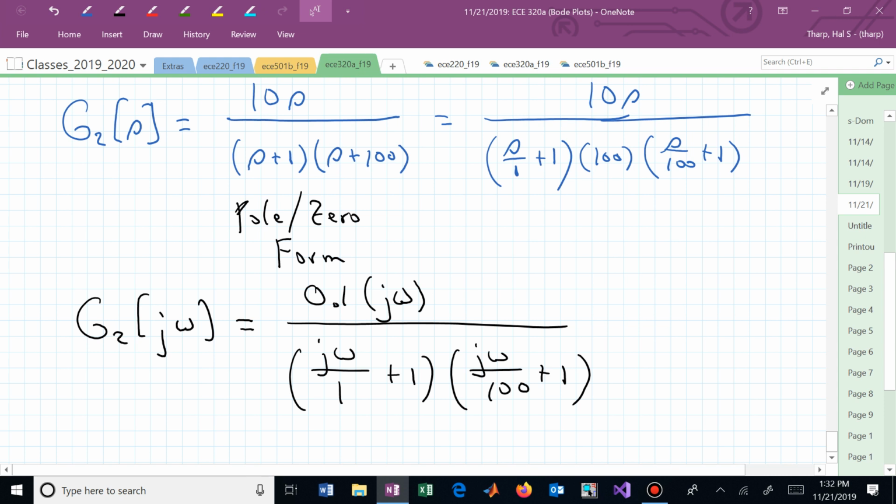Clear? Or maybe the phase curve was starting at 0 degrees at low frequencies. Where was it supposed to begin? Where the 0 was contributing, it was giving us 90 degrees. And what's another way of checking this? Now the magnitude curve, you say your magnitude curve's off too. What's the slope at high frequencies of the magnitude curve? Is it even sloping? How much is the magnitude curve sloping at high frequencies?